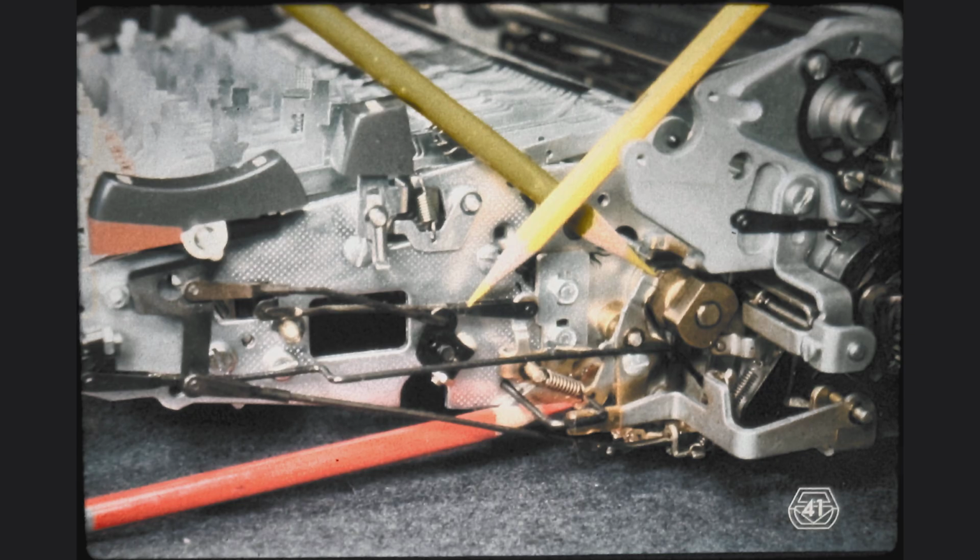The signal from the input section to the low velocity mechanism is transmitted through the link indicated by the yellow pencil, and it comes in the form of a pull toward the front, just as with the other selector latches. In the process, the low velocity control cam follower is released, or unlatched, at the point indicated by the red pencil. During the printing operation, the now unlatched cam follower follows the contour of the low velocity mechanism, restoring cam, indicated by the green pencil.